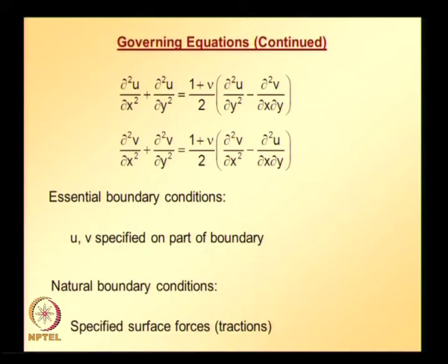And when I made the statement that the specified surface forces are first order equations, that is based on what we did in the last class, that is, express tractions in terms of stresses and stresses in terms of displacements via the stress strain and strain displacement relations. Finally, we can see tractions are related to the first derivative of displacements, which are natural boundary conditions.